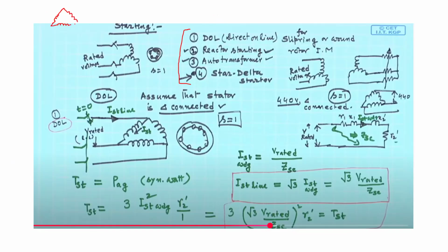So stator of your machine, let us say this is squirrel cage induction motor. So rotor is like this in the form of cages, and here you have the stator of the induction machine. Now let us say in the normal operation, the induction machine will be running in delta connection. Now in starting, what you will do, you will make the connection such that it will be connected in star, okay, for starting, but under normal operation it will be brought back to delta.